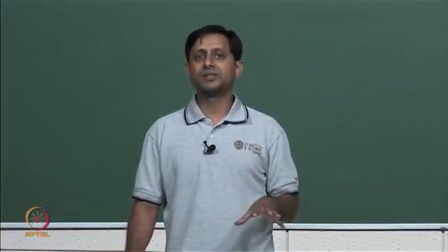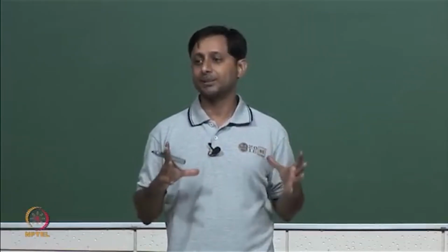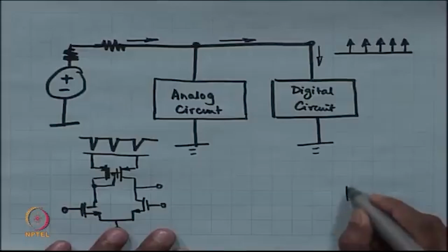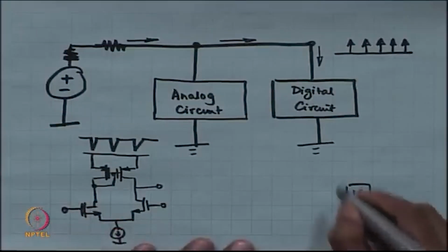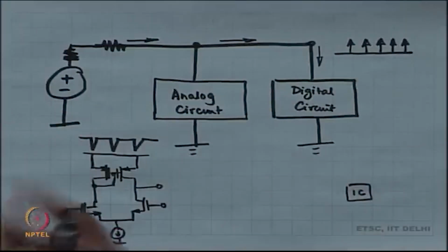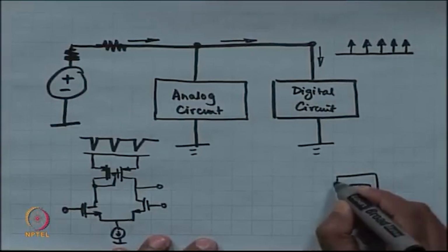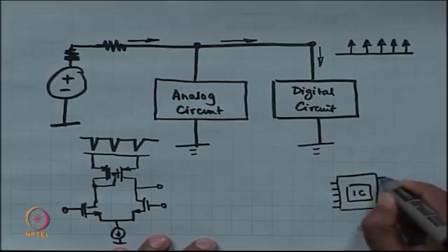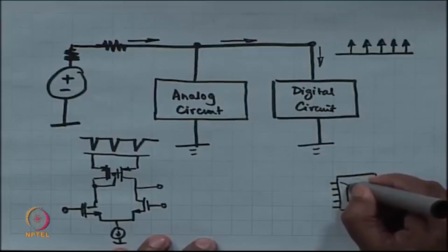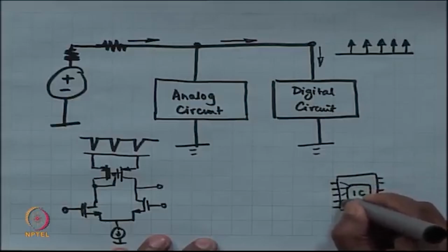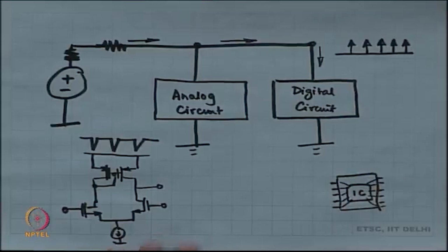Typically, when you make an integrated circuit, the integrated circuit is going to be packaged inside a package, right. You have got an IC, and then this IC is going to be packaged inside a black plastic package, which you are going to buy, right. That black plastic package is slightly bigger, and there are pins on the black plastic package, and the actual pins from the IC are bonded to that plastic package through these thin bond wires, which are made up of gold.